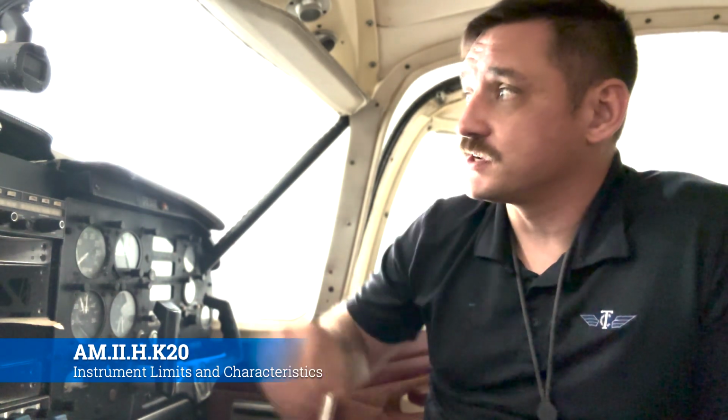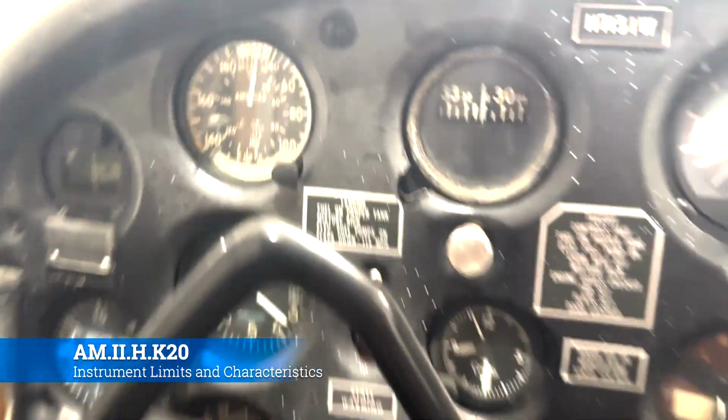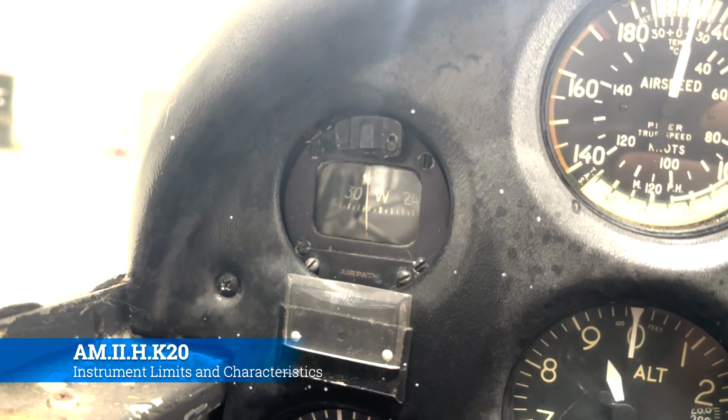Now, the next category of instruments is navigation instruments. These are instruments like the compass, or the ADF, or the VOR, or any number of things. Nowadays, a lot of times your navigation instrument is going to be just a panel, like in the Lear, it's a Garmin 430. It's just a flat panel that tells you where you're at, what altitude and speed you're going, and that also gets hooked into a system called ADS-B, which transmits that information out to the wide world, so that everyone else can know what we're doing. We'll get into that when we talk about communications and all the complexities that lie in that.